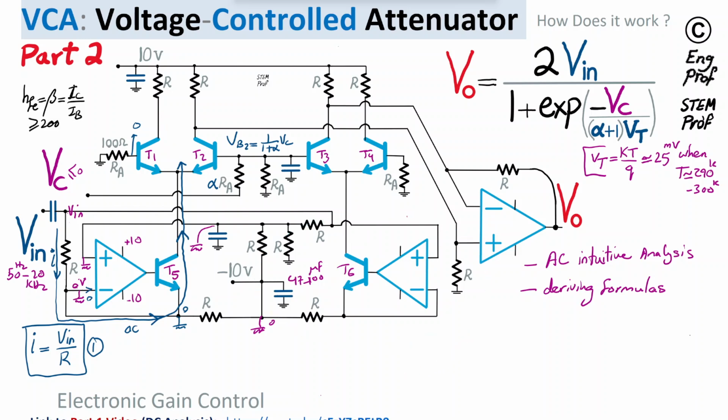So we talked about the impact of op-amp 1. Similarly, op-amp 2 has the same situation. So the Vin, this is a DC decoupling cap or AC decoupling cap. When AC is there, at the frequencies of the signal of interest, 50 Hertz to 20 kilohertz, this cap is short.